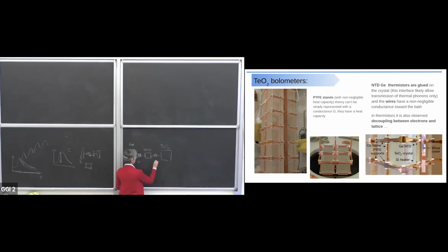And these two thermal conductances are contact conductances, and they have a dependence on temperature, and you also need to know, which is not easy to evaluate, the effective surface that is in contact between the two materials.